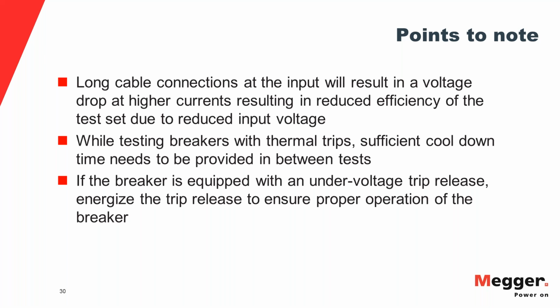While testing breakers with thermal trips, a sufficient cool down time is required. For testing of MCCBs, NEMA AB4 says that if you're going to repeat tests on the same poles, you need to wait for a period of 20 minutes between tests.